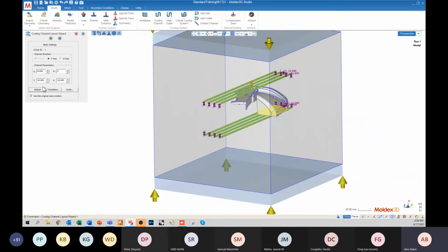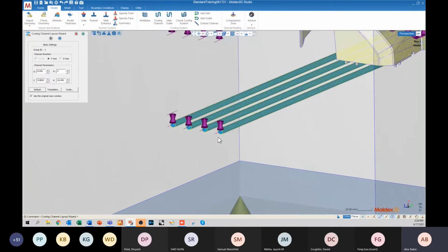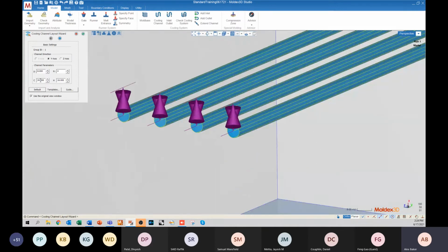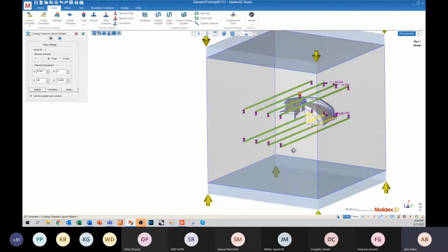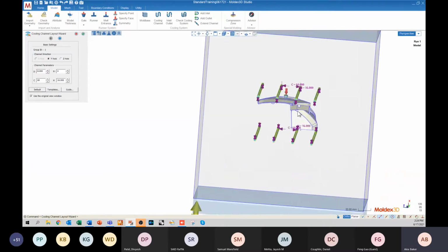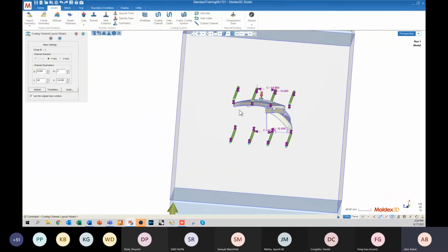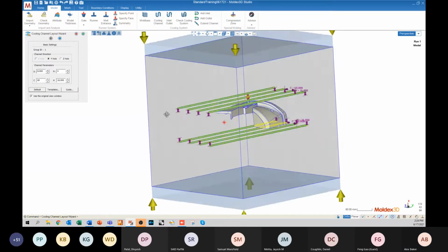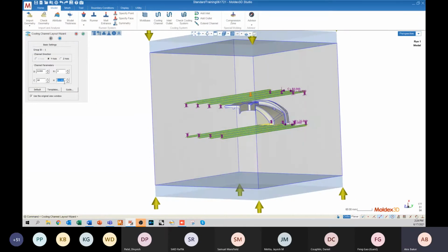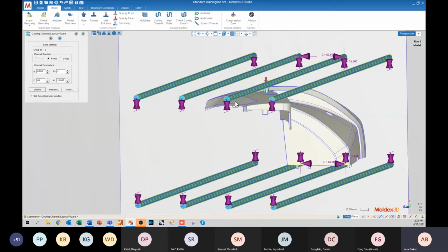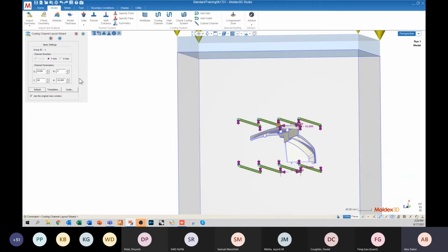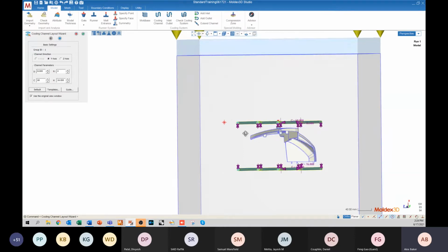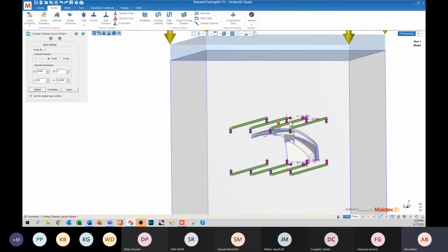C is what we call the pitch. The pitch is the distance between the cooling channel centers. So this just allows us to maybe space out the cooling channels a little bit more. Maybe I can cover my entire parting area. And then H is the distance from the cooling channels to the top or bottom most surface of the geometry. And out of these 4 channel parameters here, the height dimension is the most important if you're designing a dummy cooling system like this one.